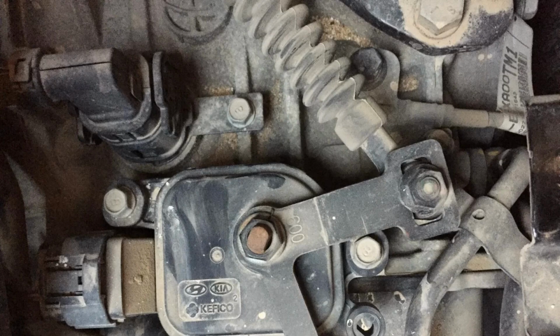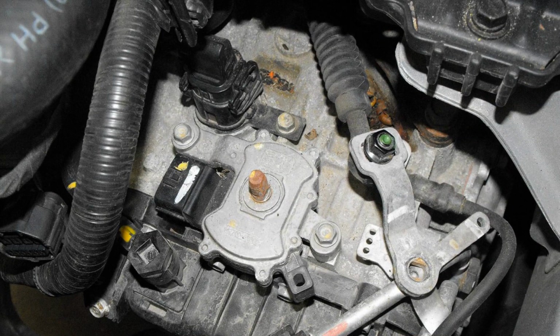How to eliminate or clear fault code P0705. Some suggested steps for troubleshooting and correcting fault code P0705. Change the ATF fluid and filter. Top up the transmission fluid to the required level. Flush to clean the internal transmission ducts. Test, if necessary, by replacing the faulty transmission range sensor. Troubleshoot mechanical faults inside the transmission. Check connectors and wiring. Flashing or replacing the PCM.